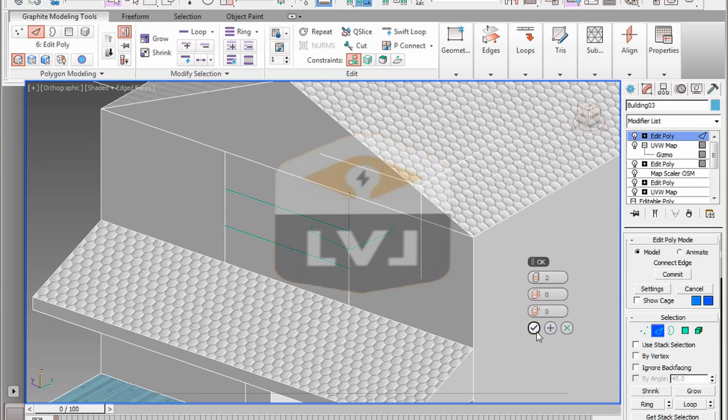Right now the window is a little bit narrow, so let's adjust the height. Click on only the top new horizontal edge. Then, in the main toolbar, click the Select and Move tool. We want to make sure that we restrict the movement only to the Z-axis. So make sure you pick right on top of the Z-axis of the gizmo, and it will highlight yellow. Now click and drag up to move the top edge up a little bit.